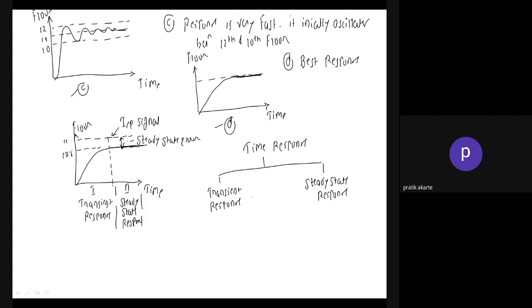Now, we can note that the output settles at 10.5 instead of 11. That error is known as steady state error. We'll be talking more about steady state error as we progress. But for the time being, remember, if we are not achieving what is desirable and that undesirable condition remains for an entire lifespan, that is called an error, a steady state error.